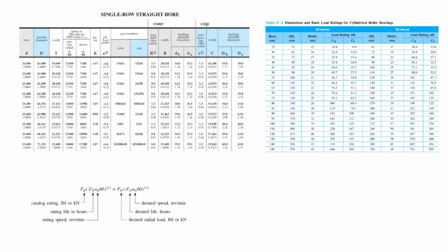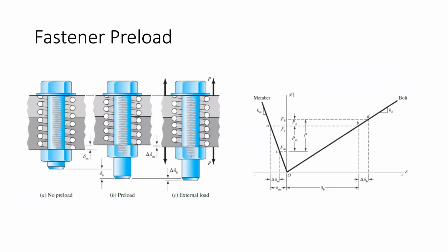And what actually happened this year is that on our front hubs, you have the front hub bearing and the hub rotating in it, and there's a fastener bolt that preloads the two together, right? But it turns out the preload amount was super small. So they used a lock nut and just tightened it down to the right torque, and we said, oh, we've got the right amount of preload. But when you're not preloading your fasteners sufficiently, even though we were hitting the right preload on the bearing, they just back out over time because the system vibrates so much. So it's actually a really complicated problem sometimes.